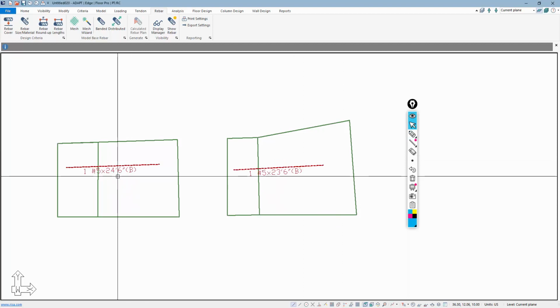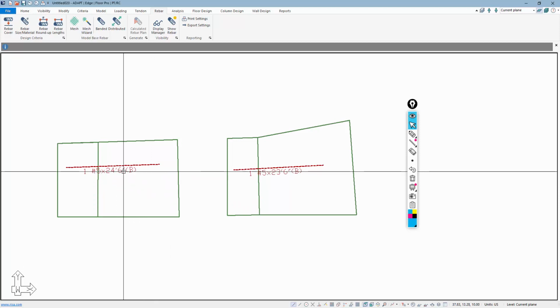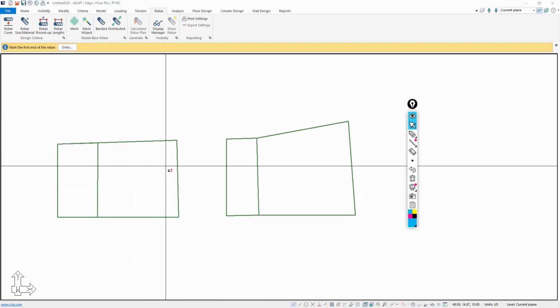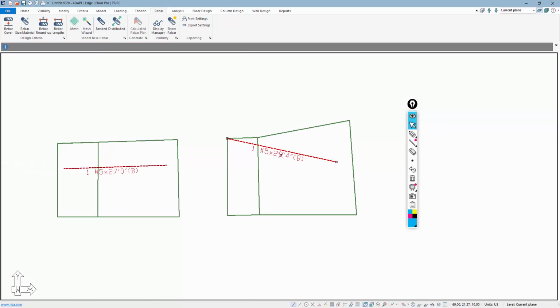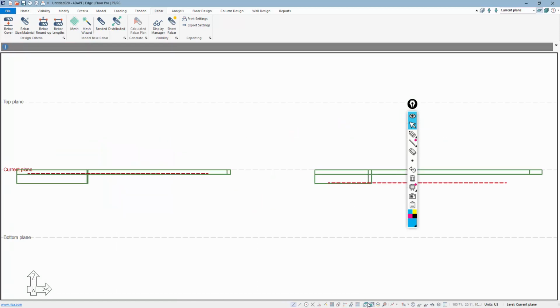Now the next example will be banded reinforcement. This is really just grouped reinforcement. So let me just delete these two bars. If I take banded and I just put a bottom bar here and here, again, because it's passing through two different slabs, we get the similar condition. We get one that's referenced from slab 1, and then the other one is referenced from slab 3.